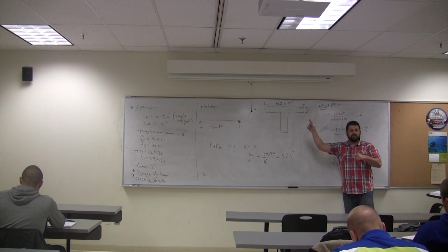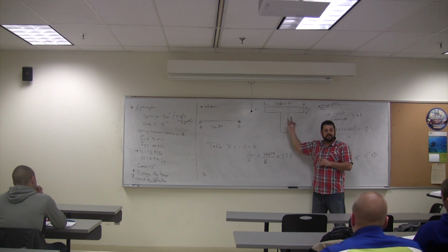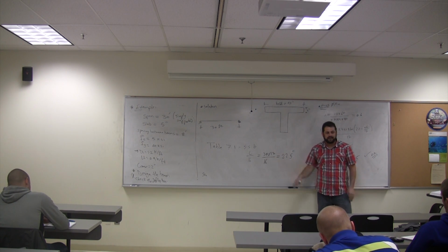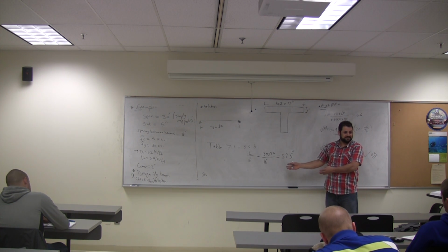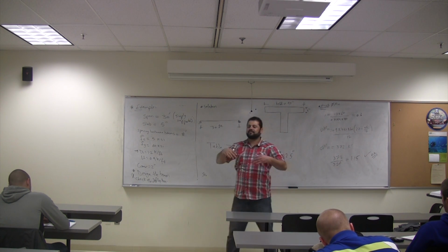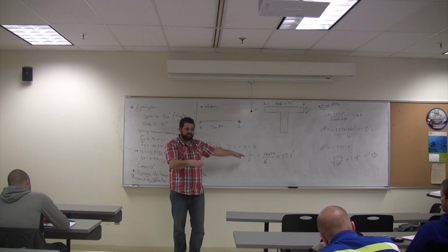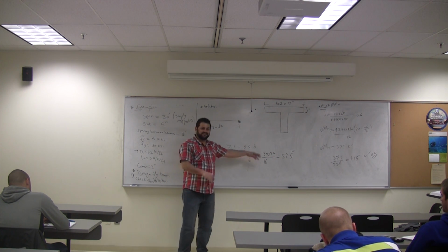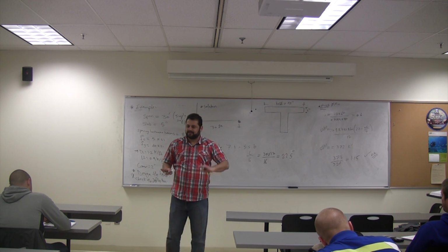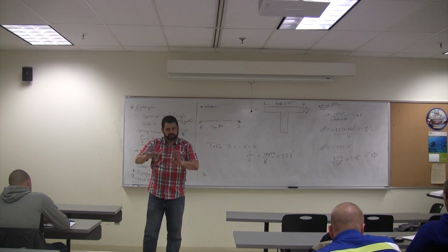So if your beam depth H is greater than this number, deflection will be okay. So is deflection okay? Believe it or not, that's a check. And some guys, even from the beginning, pick H based on this table because they are scared to check the deflection. So they come here and say okay, L over 16, let me use H equal 24 for sure. Then they go back and calculate the area of steel. That's absolutely good design.